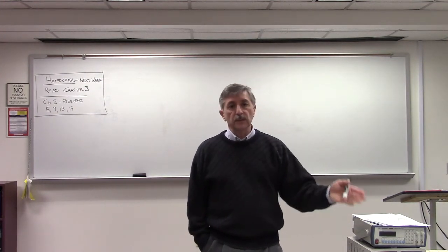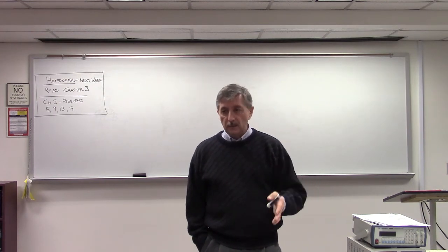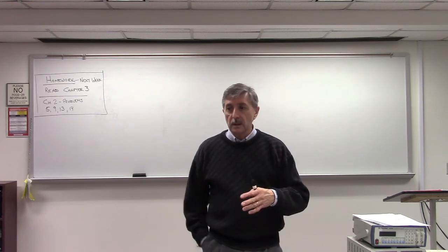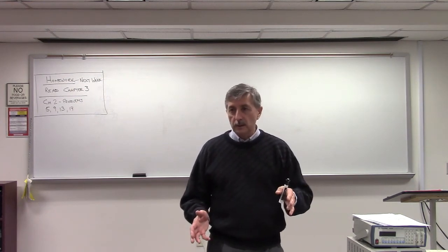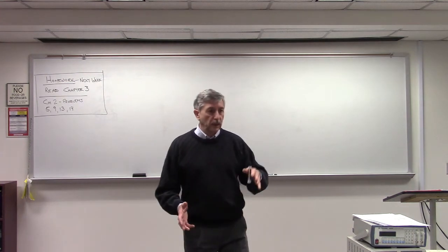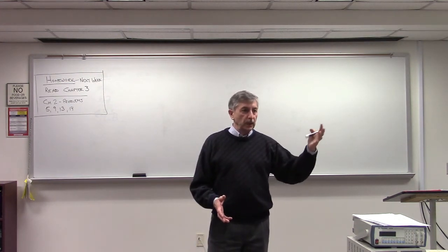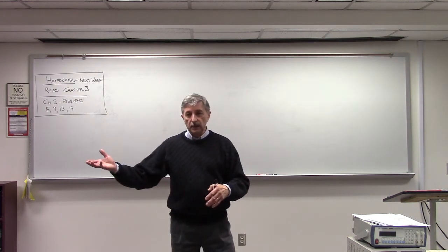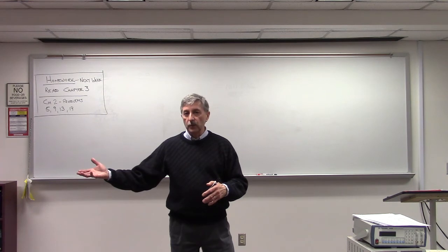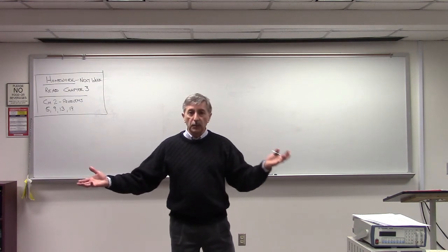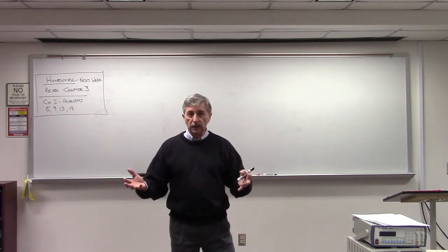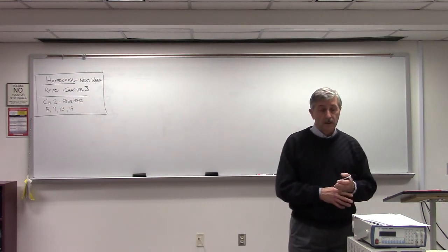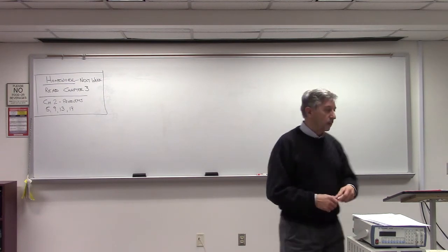So you have to be able to start out with the manufacturer's data and convert it to dimensions that you're looking to work with. Sometimes you have the same parameter over here in one set of units, and sometimes you have the same parameter over here from another manufacturer, same parameter but different units, and you have to be able to convert those to one common set of units so that you can do your calculations. And so the way you do that is dimensional analysis.